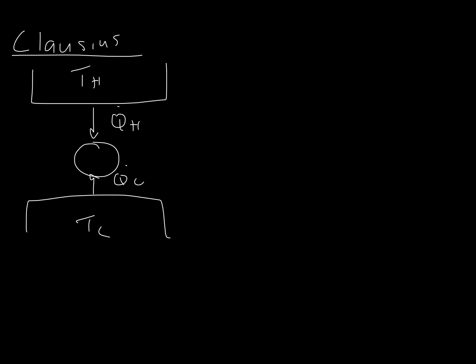Sometimes you'll have to be a little bit flexible, especially when you're dealing with a heat exchanger, because you'll have heat going from one to the other process, and if you don't keep that nomenclature consistent, your math won't add up. You have to have heat going out of one and into the other, so it'll have to be minus in one balance and plus in the other. So the arrow direction doesn't matter. As long as your math is consistent, everything will work out. And if you screw up the arrow direction, all that's going to change is that it'll be a negative sign. That's it. Okay. So this is our process.